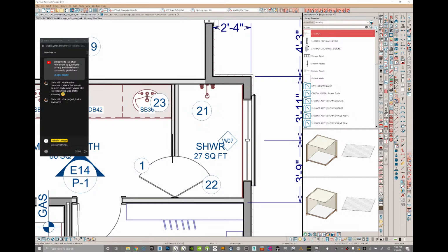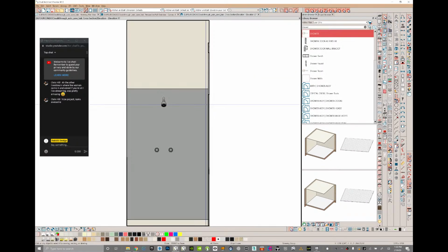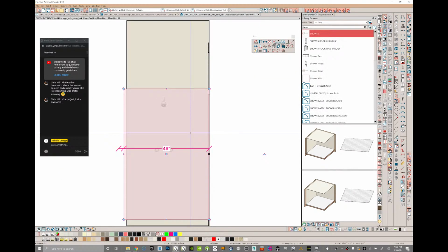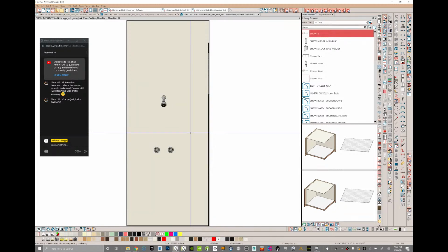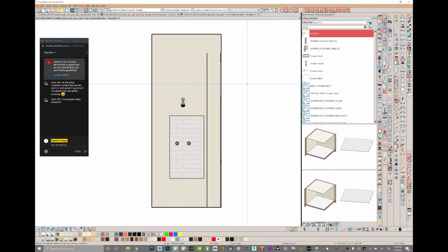And let's pull another elevation. We're going to get our backsplash in on this side, and we're going to make sure it passes our little half wall there. Don't know what this is. Looks like they tried to draw backsplash. Going to get rid of it. Same thing. Let's just draw that polyline, 105. Great thing about X-13.